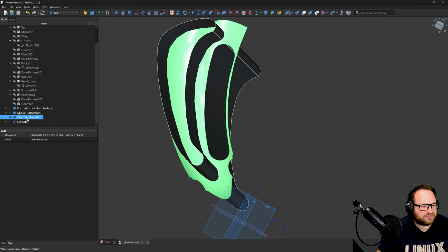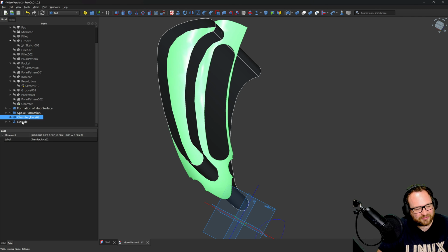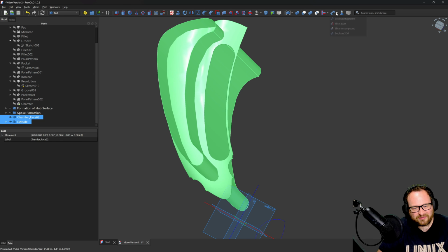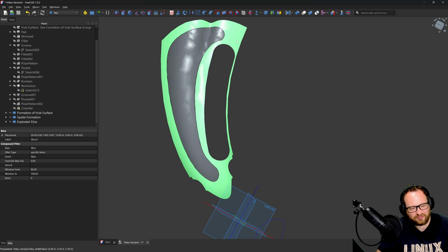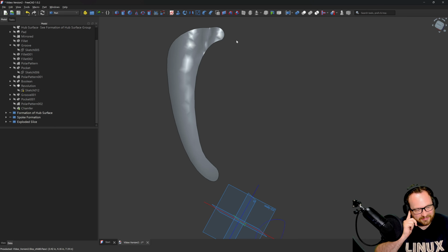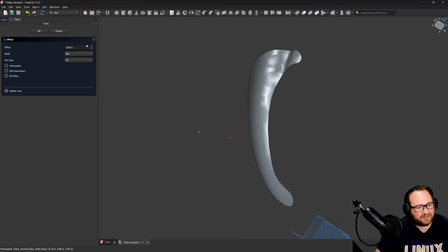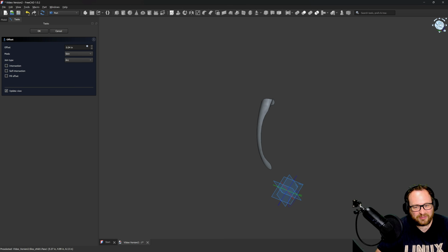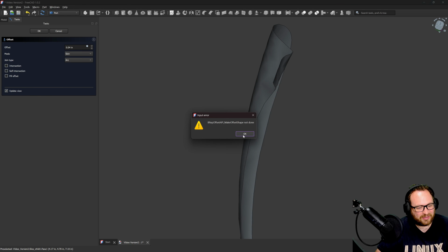So I'm going to choose first off my face that I want to keep, and then I'm using this extrude as a trimming tool, and we're going to say slice apart. And just like that, I can choose the surface that I no longer need and either hide it or just hit the delete key and delete it. That slice apart tool has been one of my favorites for a long time. Now we can select this surface and create an offset, and that's already not looking good to me because I don't see an offset happening. So if I try to say okay, nothing happens.